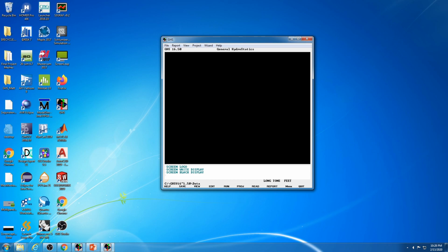At any step along the way, if you get lost or are confused, the menu that you will find most useful is the Help menu, which provides quick access to nearly all of the GHS user's manual. It is organized by command name, making it a breeze to look up a command's description and parameters. Moreover, there's a global search feature allowing you to search the entire manual for any word.